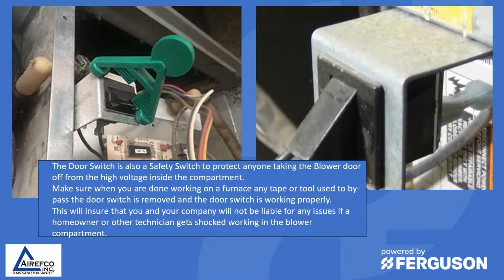The door switch is also a safety switch to protect anyone taking the blower door off from the high voltage inside the compartment. Make sure when you are done working on a furnace, any tape or tool used to bypass the door switch is removed and the door switch is working properly. This will ensure that you and your company will not be liable for any issues if a homeowner or other technician gets shocked working in the blower compartment.